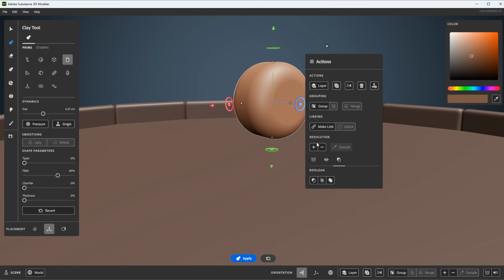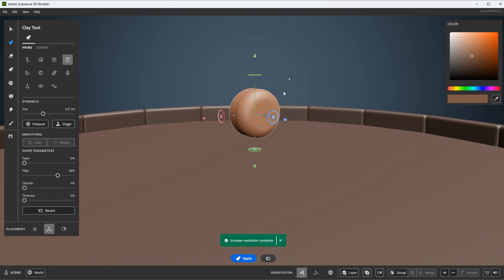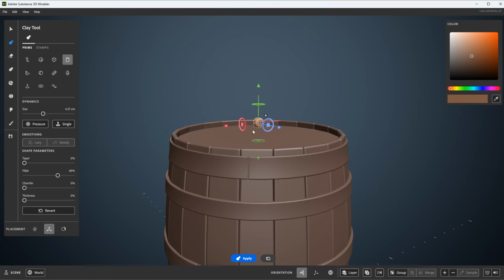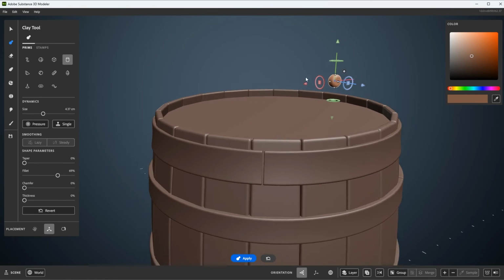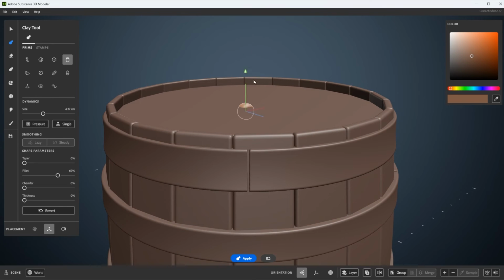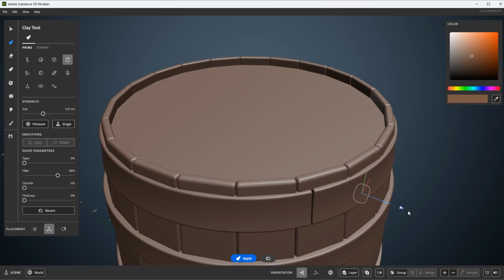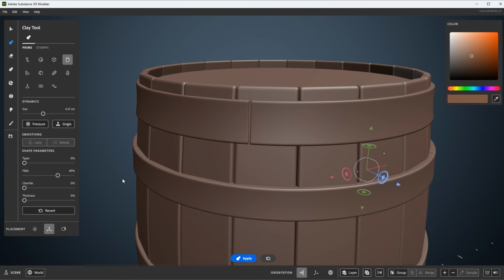And then let's right click and take a look at that resolution. You can see it's super low. So let me just click a few times in my resolution just to update this. And honestly, for what I'm doing here, that's going to work. So at this point, I'm in the Gizmo mode. And I could, like I said before, move this around, axis by axis here and just position it. Or this is a great spot to use the placement mode here of surface.